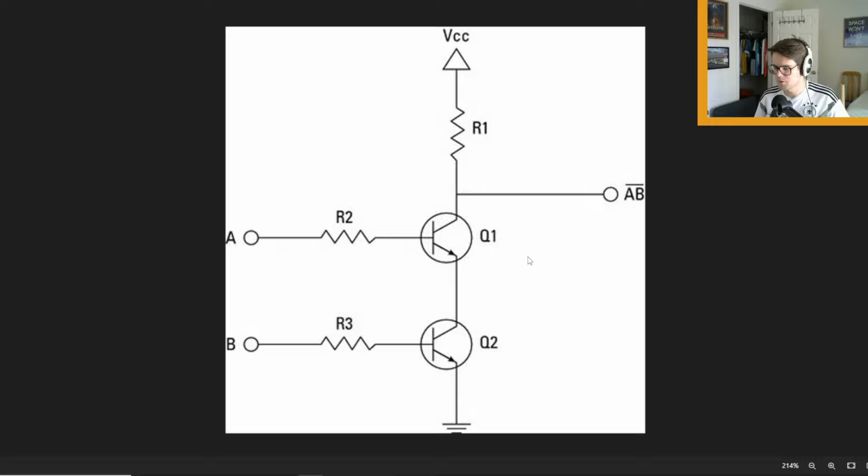I was very frustrated with my previous logic gate designs, and so I went back to looking at the basics to see if there's any way I could translate this into duck game. Fundamentally, from my understanding, a NAND gate is the basic building block in most digital circuitry. For example, from my last video, we could build a register out of 2 OR gates and 2 AND gates, or we could just do it out of 4 NAND gates. So if you're reusing the same structure over and over again, it makes design significantly less complex.